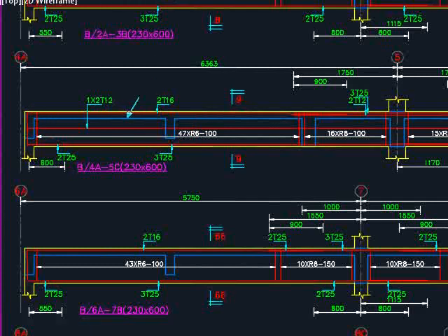The slab here, solid line, means that you're going to see the edge, and indicate the amount of reinforcement bar, and indicate the columns. There are columns not extended to the upper side of the beam, and there are columns actually penetrating through the beam. And this column here will need to be in accordance to the size of the columns as given in the key plan.